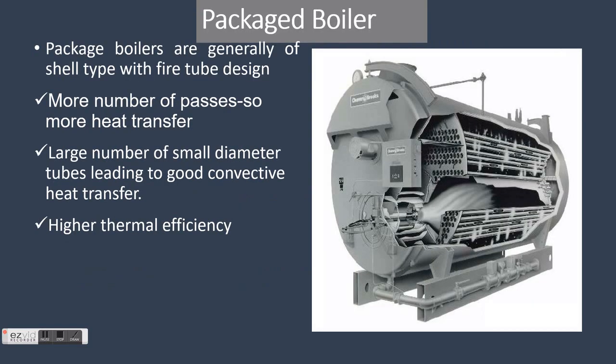Please go through it. Next type of boiler is the package boiler. The packaged boiler is so called because it comes as a complete package. Once delivered to site, it requires only the steam, water pipe work, fuel supply and electrical connections to be made for it to become operational.